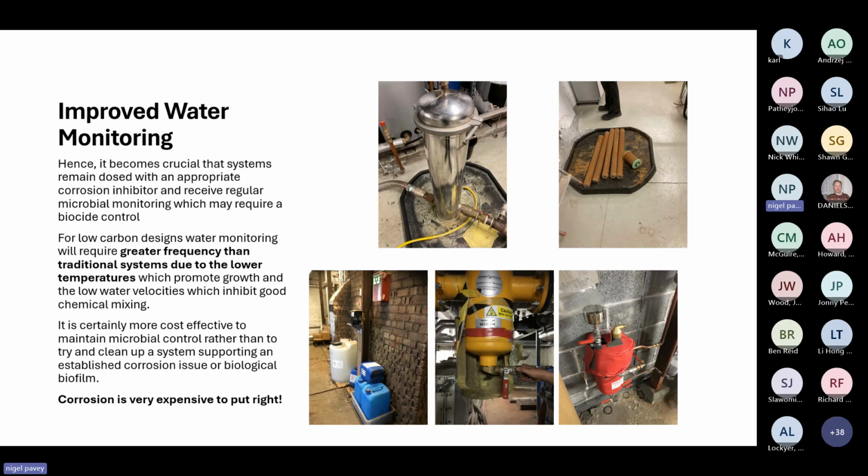So, in this pipework journey, I've touched upon heat, I've touched upon resistance, I've touched upon frictional fittings and how you need to consider those. And the one that people do forget is improving water quality. It's fine to design a system, it's fine to get to PC, get an O&M, and then think the job's done. But ongoing water quality and who's responsible for that is really important.